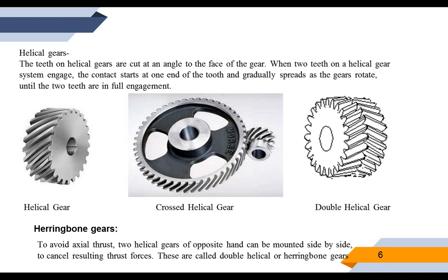These herringbone gears are most of the time used in common applications in power transmission. They utilize curved teeth for efficient high capacity power transmission. This offers reduced pulsation, due to which they are highly used for extrusion and polymerization. So herringbone gears are mostly used on heavy machinery. So these are the different types of gears.